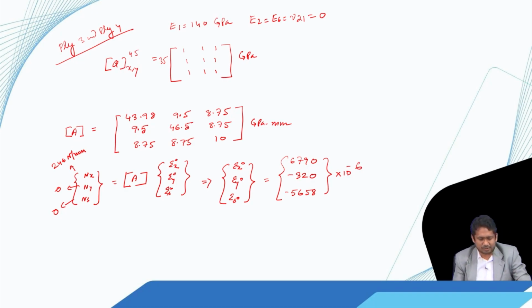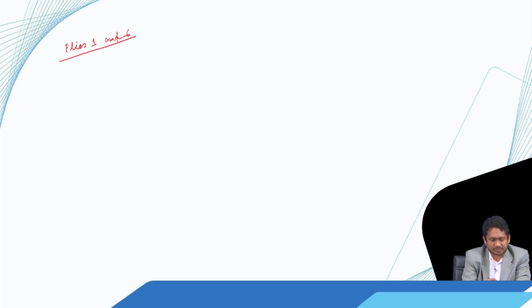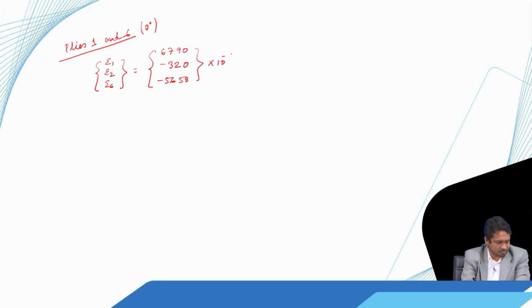Now, let us look into ply 1 and 6, those are the plies yet to fail. So, plies 1 and 6, and those are 0 degree plies. So, for them epsilon 1, epsilon 2 and epsilon 6 are same as epsilon x, epsilon y and epsilon s. So, 6790, minus 320, minus 5658 into 10 to the power minus 6.